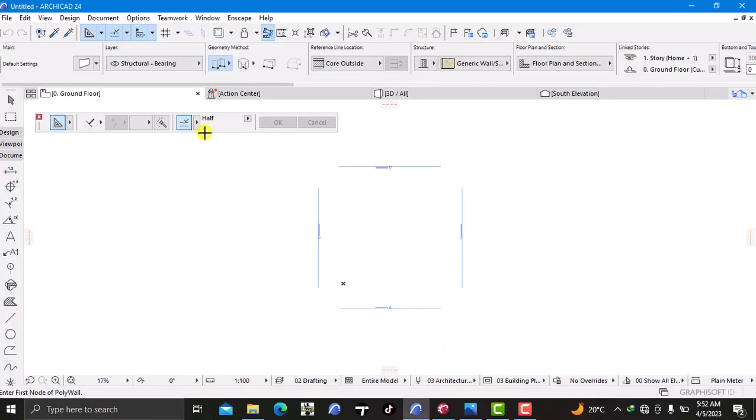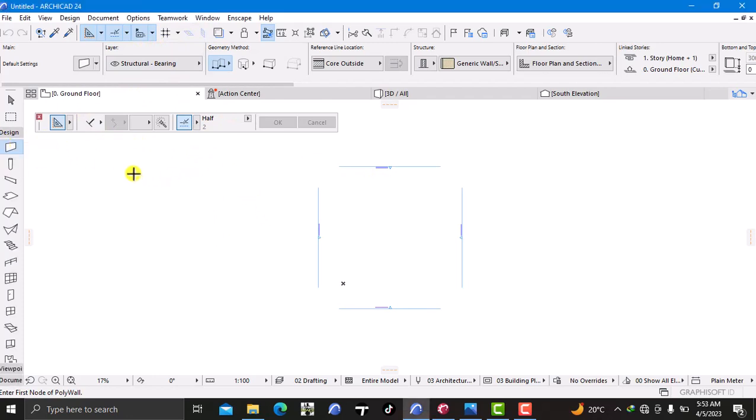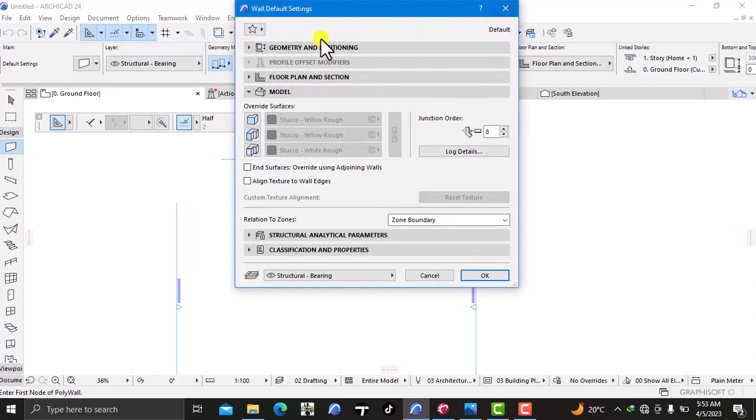So I've already opened up my ArchiCAD software and I'm brought directly to this menu. As the norm, we start by setting the orientation of the walls of my plan. I'll go to this wall tool, click it, and set the height of my wall and what I want to use for my walls, my textures.